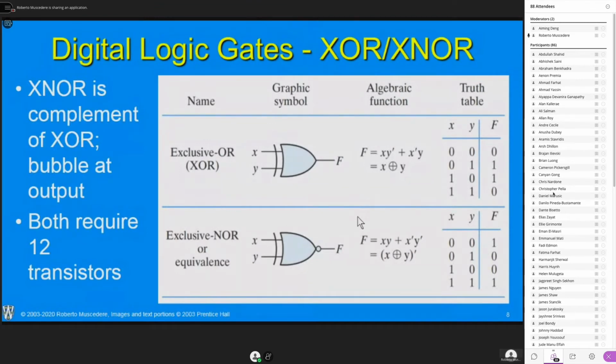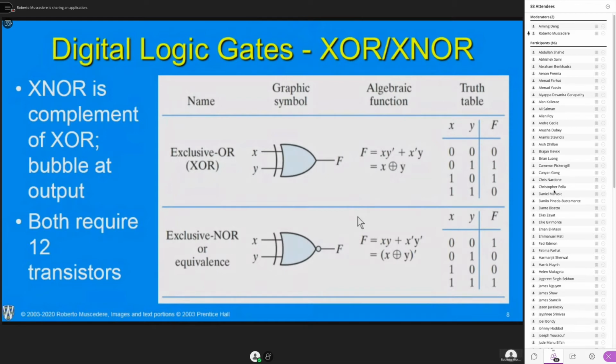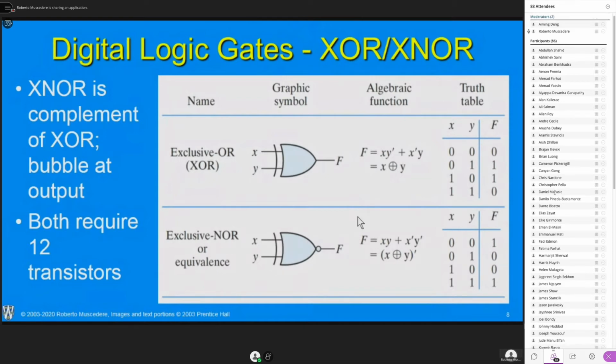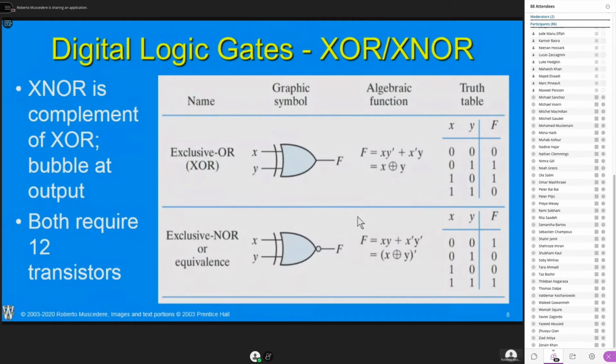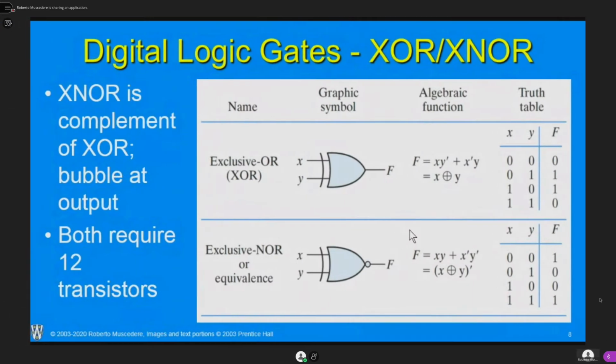Steve Wozniak and Steve Jobs were looking for work again before they started Apple. One of the jobs they had was reducing circuit sizes for Atari. Atari would give them a schematic and say, okay, reduce the number of chips here. What they would essentially do is this Boolean logic reduction, changing all the AND and OR gates to NOR gates or NAND gates. That's how they made the circuits smaller. It's just that simple. They just applied all these reduction techniques.